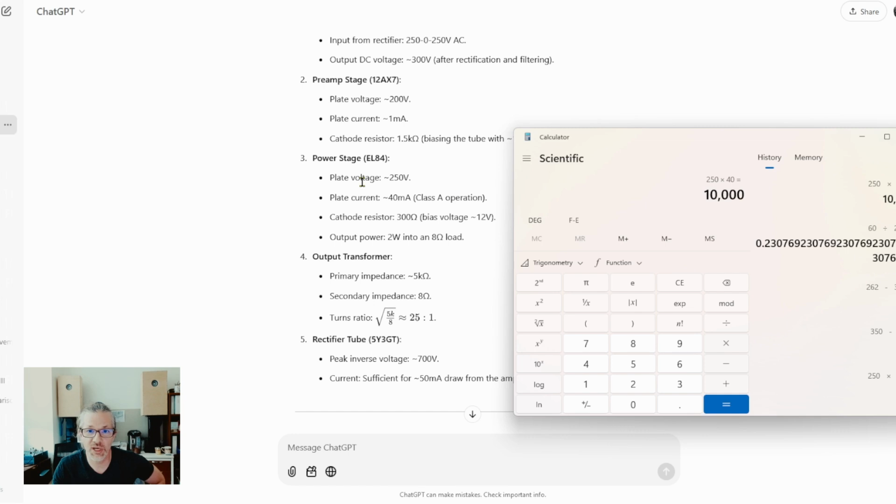This tube is rated at 12 watts, so it means that we are running it below 100% plate dissipation. So even if we add a little higher plate voltage, higher plate dissipation, it will be still fine. However, for how fine we'll be doing, let's see.